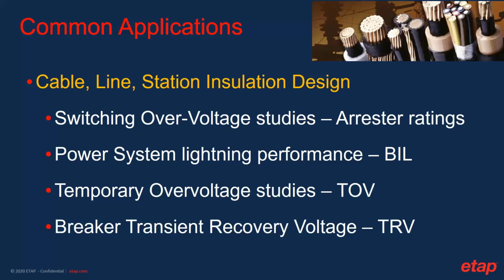Similarly, it's common that you perform lightning studies. If lightning hits your transmission conductor near a substation, what are the resulting overvoltages? Can your equipment and your surge arresters handle that overvoltage? So this lightning results in very high frequencies and the transients last for a very short duration. So switching and lightning are transients that last for nanoseconds or a few milliseconds, fast transients.